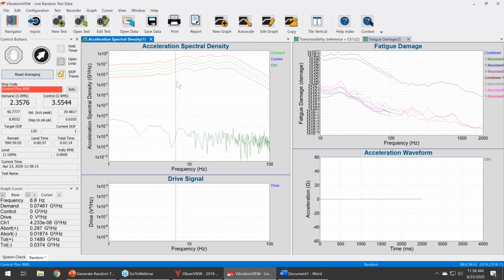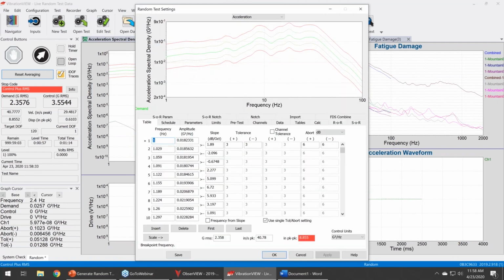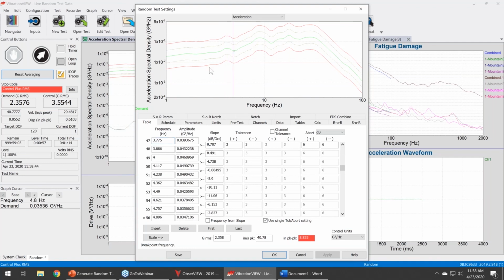But if I don't have a resonance, I'm not going to damage anything. That's high cycle fatigue, designed around high cycle fatigue failures. So minimizing the amount of displacement you have to do by reducing or removing that low frequency content, I'm not going to get damage replication if I am reducing these peaks in any way. So this is the amplitude that if I want to run this many hours of damage in this period of time, this is the amplitude that I need.